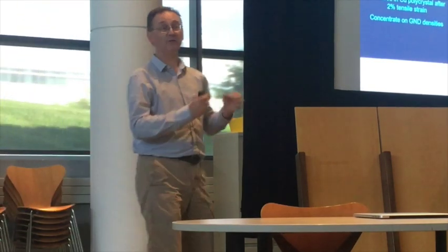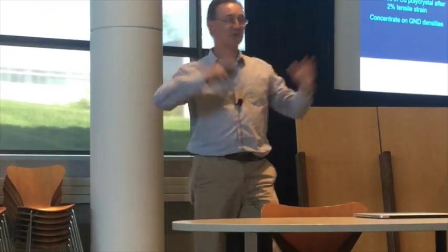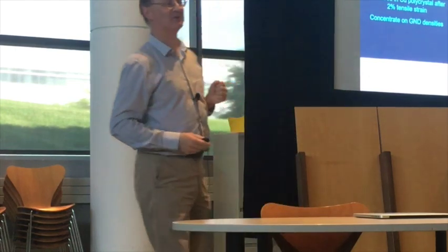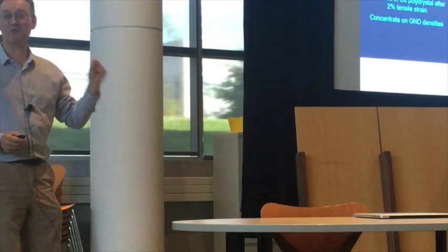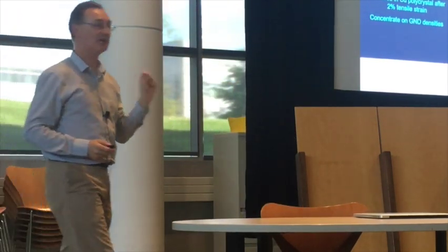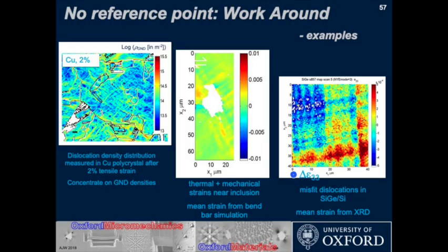Take a polycrystal deformed. There are strains everywhere, and that's kind of what we wanted to know about. And unfortunately, I don't know what the strains are at the reference point. Why we got interested in geometrically necessary dislocation densities, in part, was a get-round of fudge, an avoidance of the real issue of trying to work out what the reference state was. So you can learn some stuff.